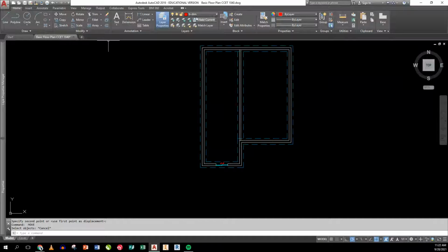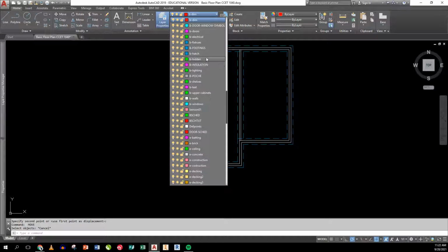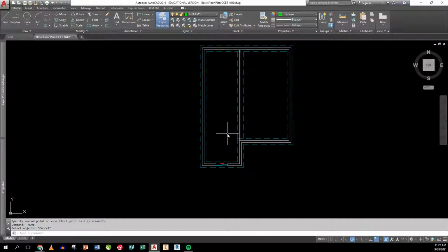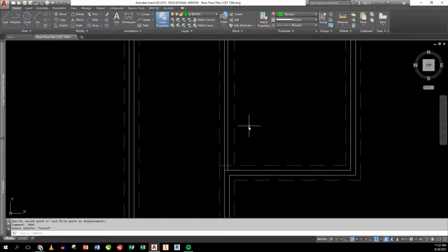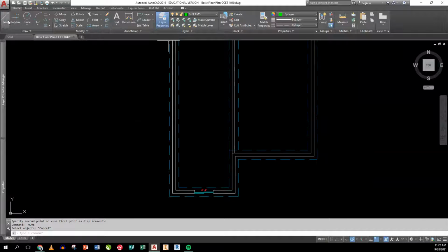Okay. Now, other things I might do that normally show up. If you look at your B, I'm looking at all of my B layers right here, and there's one I don't have made right now, so I'll probably have to make it. Actually, nope, I have one right here. So these are my joists, and I call them joists and beams. I put them on the same layer. I'm going to put in a beam that is a polyline that goes from right here on over to right here, so it just spans across.